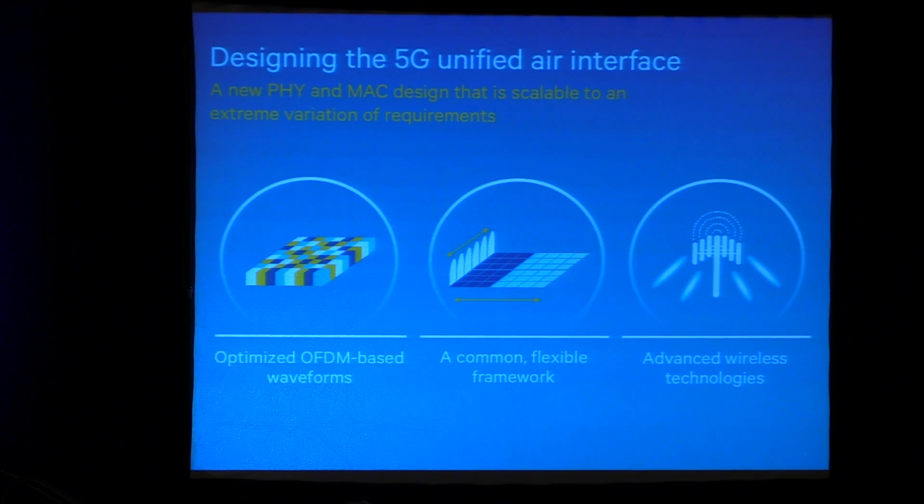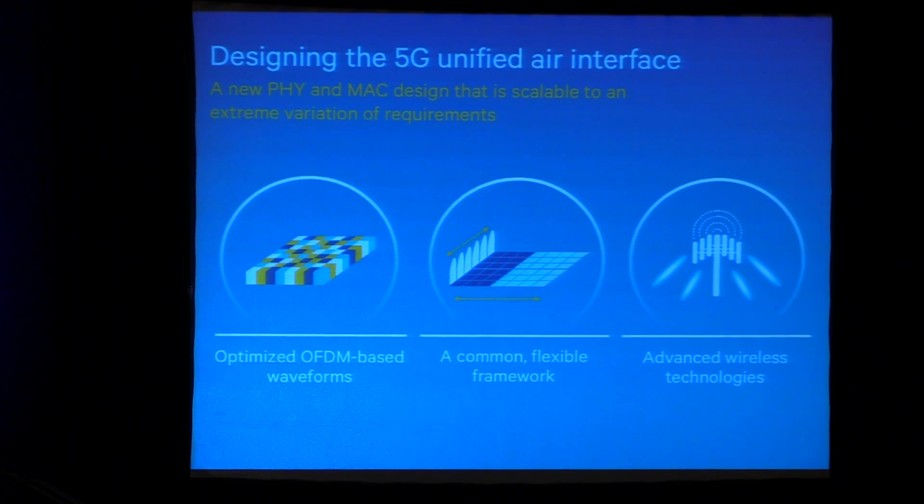We're going to start with the OFDM family of waveforms. There's a lot of reasons that we do that. You can get to wider bandwidth with efficient receivers, good resistance to multipath. You can add filtering and windowing to tailor it to different emissions requirements or make changes that allow efficient operation at very high SNR. We're going to use that as the basis for this.